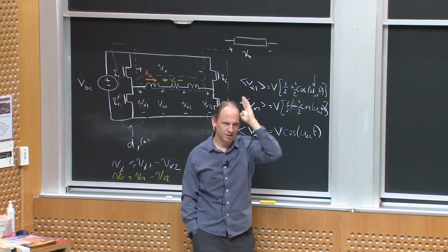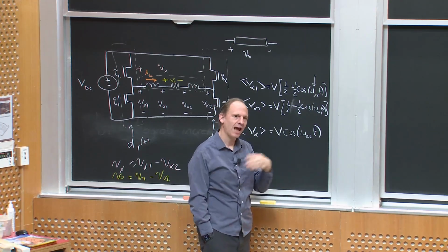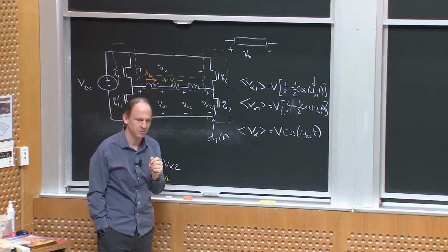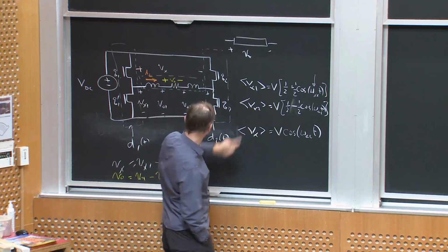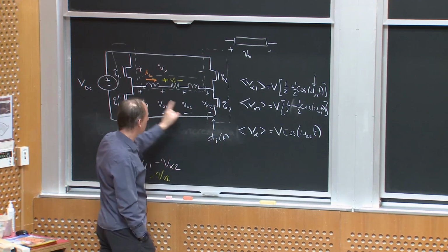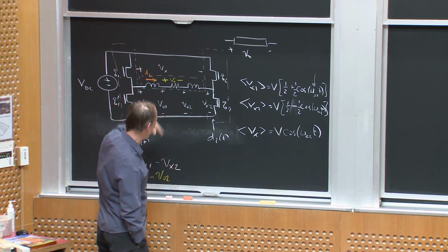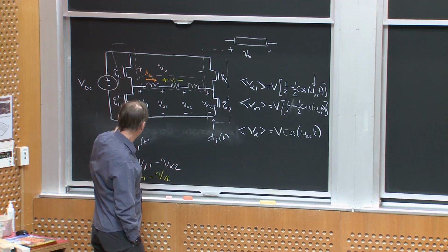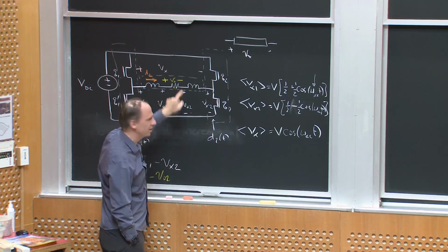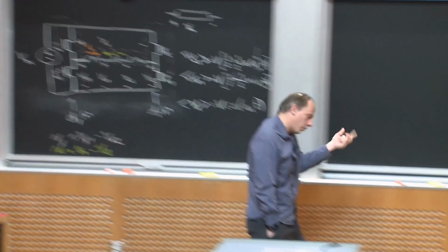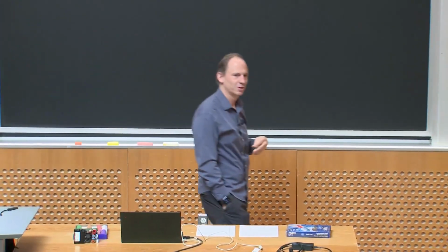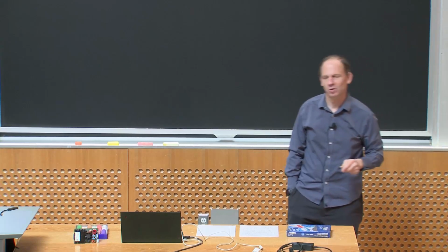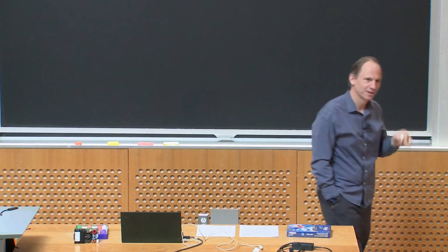So instead of being average over infinite time, it's average over just some time that's long compared to the PWM cycle, hundreds or thousands of PWM cycles. So I slowly vary my duty cycle, D of T, not within a switching cycle, but slowly compared to the switching period of the inverter and on the time scale of the AC output I want to synthesize. So if I want to synthesize music, I'd better have a switching frequency that's much higher than 20 kilohertz, the bandwidth you can hear. Or in my case, 8 or 10 kilohertz, but that's life.